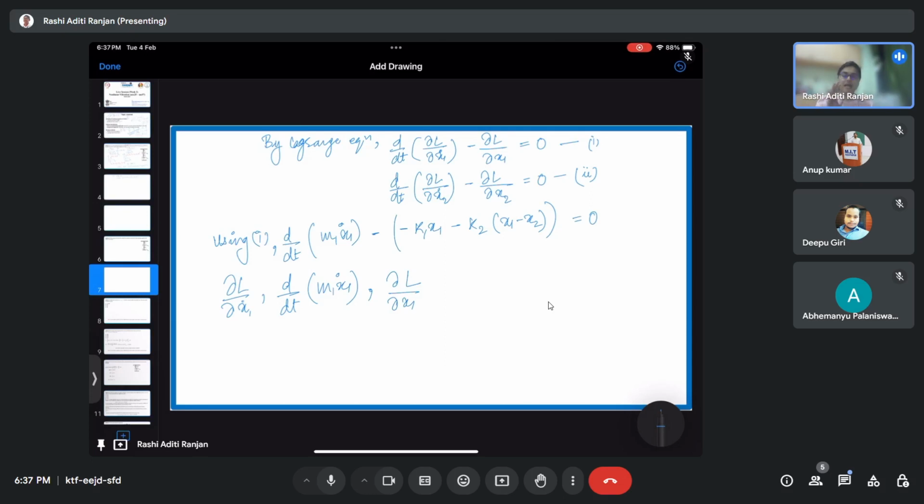Only if I consider an ideal situation can I consider the mass or the stiffness to be constant and take it out of the differentiation, as I am doing currently. I'm considering an ideal system, but that is not true for all kinds of systems. So if you have a problem in which you have to consider the property of the material, the structure of the material, or the mass and particle distribution of the material, then your mass and stiffness are going to be inside the differentiation.